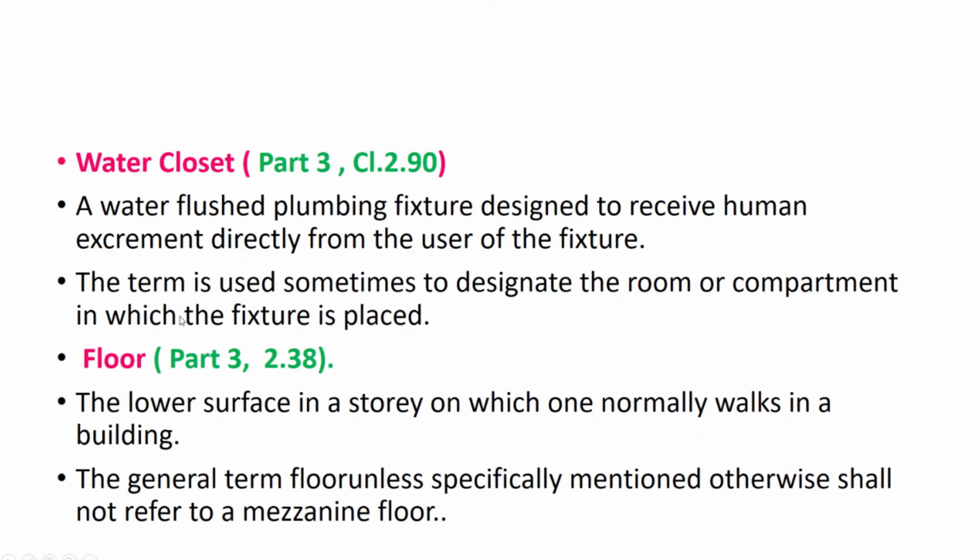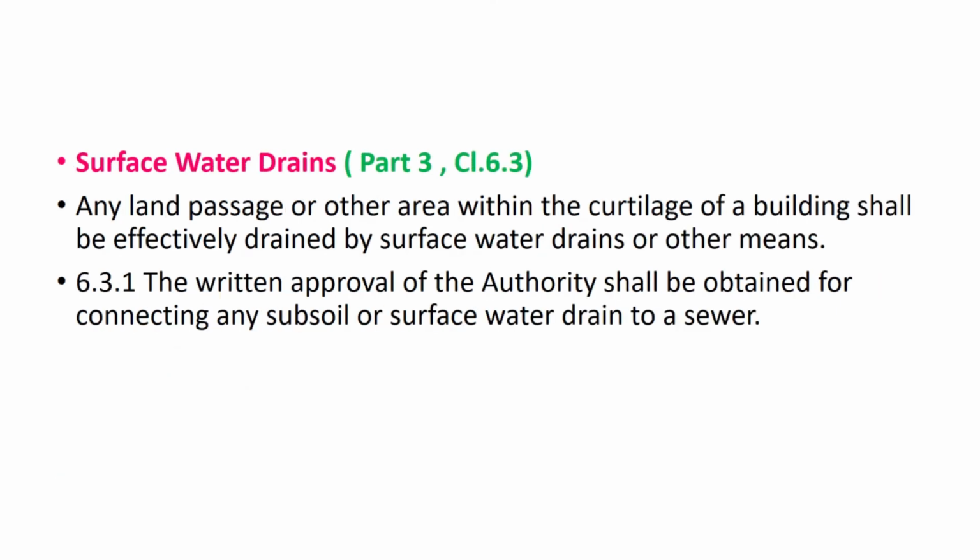This is very important because you may be founding on the pile foundation, but the depth of investigation, what they are saying, shall be sufficiently below the expected founding level of the pile. But this should not be less than 5 meters or 5 times the diameter of the piles, whichever is more, beyond the estimated pile termination level. See, normally what we do is that suppose the pile depth is 20 meters, we do investigation only up to 20 meters or so. But what he is saying now is different. Why they want to go further below?